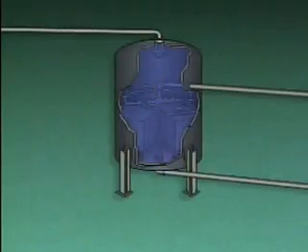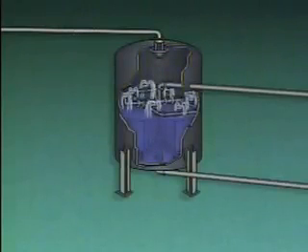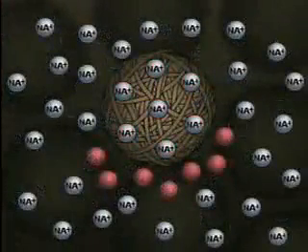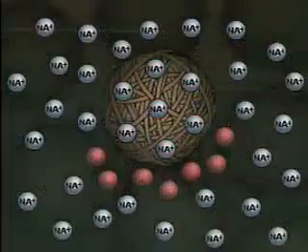In the next step, regenerating, a concentrated saltwater solution is passed through the resin bed. The overwhelming number of sodium ions in the salt water solution overcomes selectivity. The sodium ions drive the hard ions off of the resin bead sites and replace them.